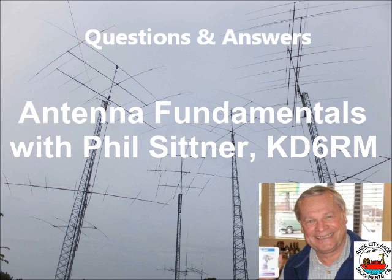Phil, yeah. If you have an SWR reading of 10 to 1, how do you reduce that to maybe 3 to 1 or 2 to 1? Or is there such a thing as doing a reduction? That's what the matching unit does. Your antenna matching unit, your transmatch. It takes what the antenna is presenting as a load, and through the use of what they call reactive components, there's a capacitor and an inductor inside of that box. And by manipulating the values of those, it reduces the SWR to your transmitter.